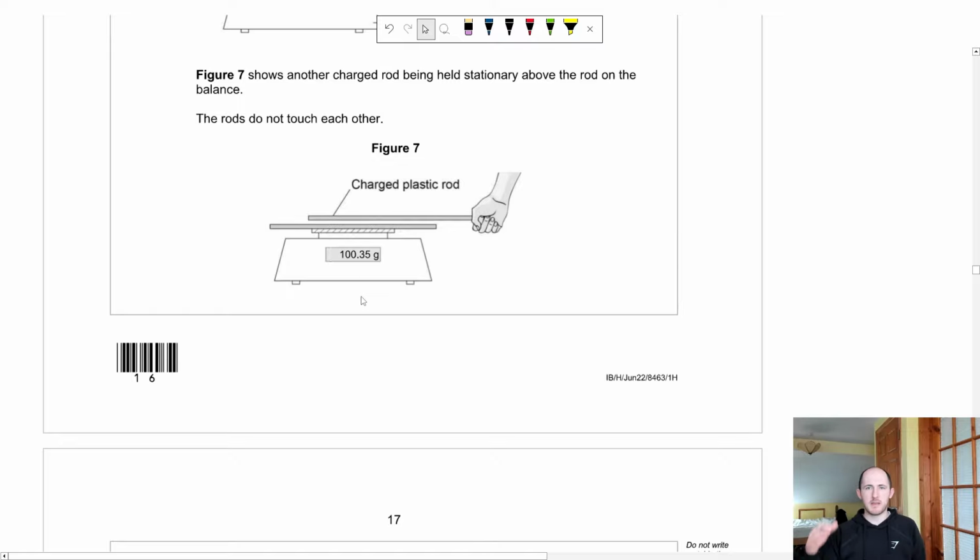So it obviously isn't measuring the mass of your hand, because I could put my hand on it and it measures, let's say, 5 kilos. I could then push down and measure 10, 15, 20 kilos. So it's not measuring the mass of my hand, it's measuring the force of my hand on the balance. So that's the really key thing here. These weighing scales measure force, not mass. It's just that what it does is it takes the downward force and divides it by 9.81 or 10, or whatever value you use for gravity, to turn it into a mass.